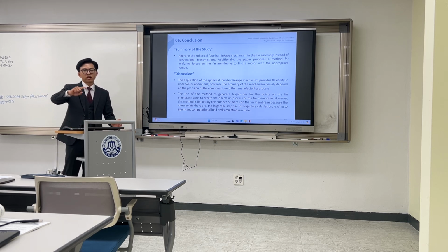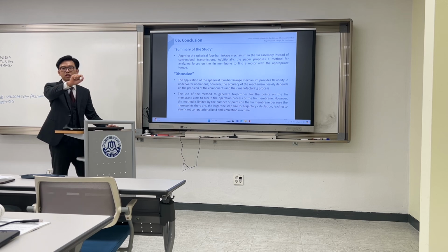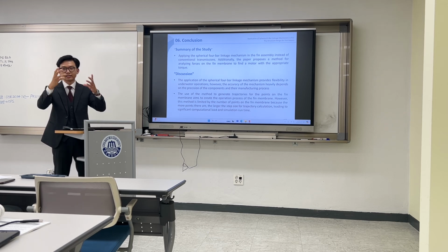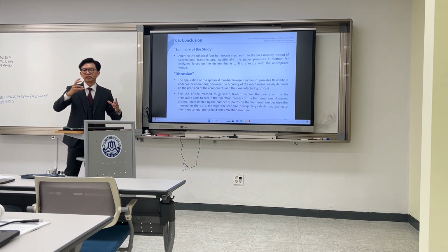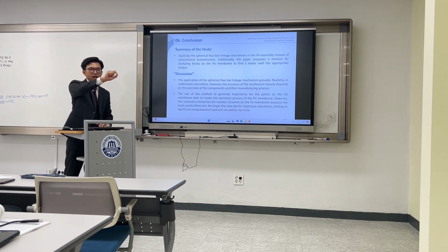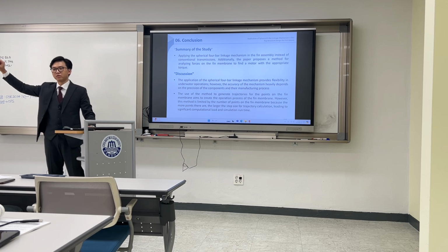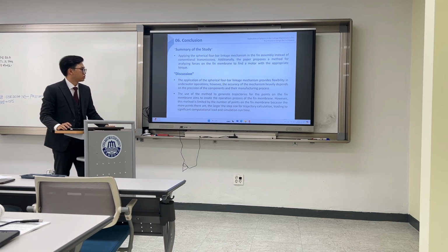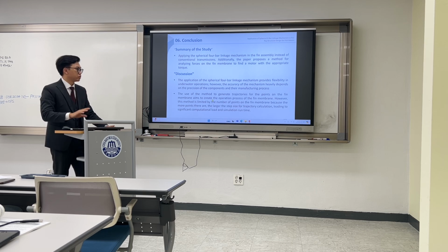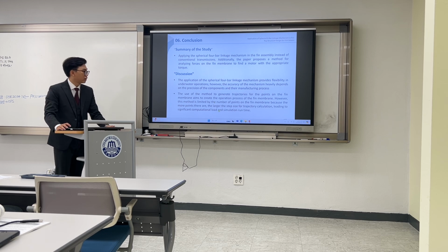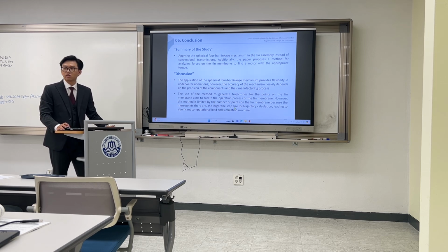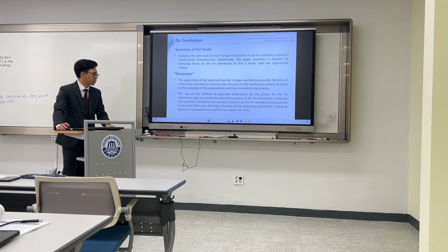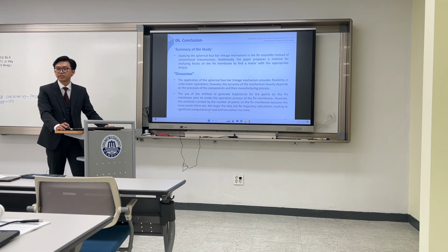You can ask how we can know the point underwater. We don't know that because we don't have any eyes on them. I mean eyes, meaning sensors or something like that. Like, how do we know the fish is moving? We don't know that. So the algorithm we build here creates the operation process for the fin membrane. However, this method is limited by the number of points on the fin membrane, because the more points there are, the larger the step size for calculation, leading to significant computational loss and simulation runtime.